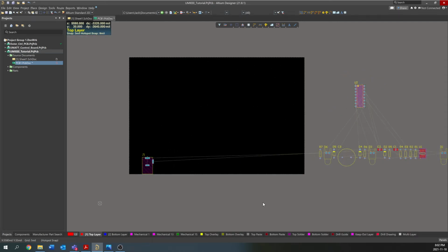It updates automatically. Another design tip here is to regularly go between the 2D mode, which is what we're in right now, and the 3D mode. This is accessed by hitting the 2 or the 3 number keys on the top, 1, 2, or 3. The number 1 mode is the board size definition mode, and that allows you to change the board size.